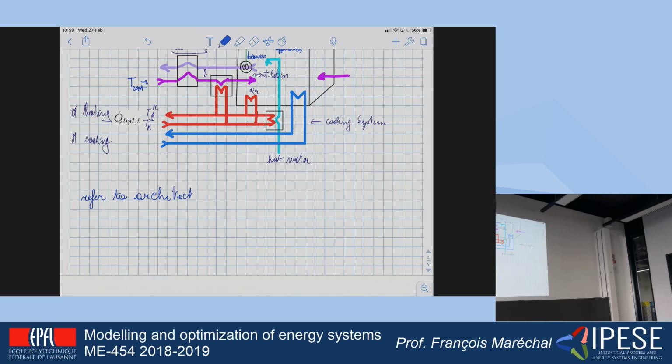Do they have insulation materials or not? What is the quality of the windows here? Is it double glazed, triple glazed? What is the material that is used here? They will in fact come back to you and say, give me how the building has been constructed, and I will give you the amount of heat that is needed.